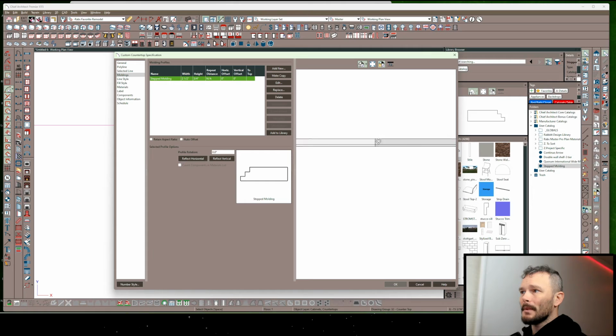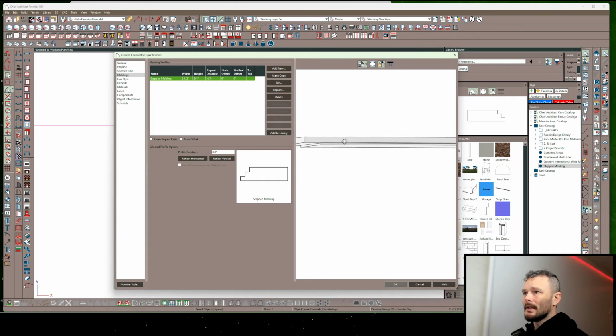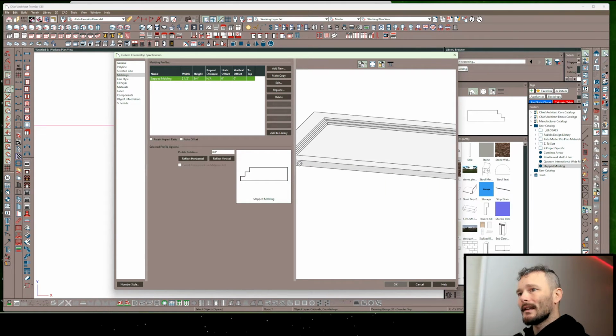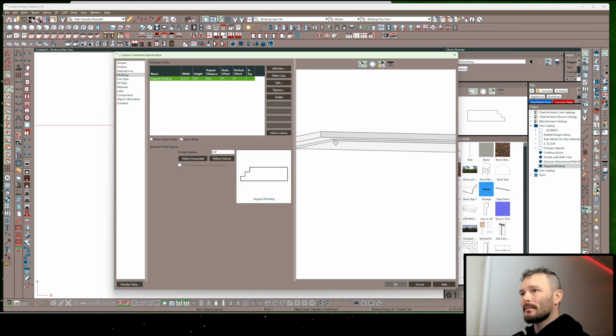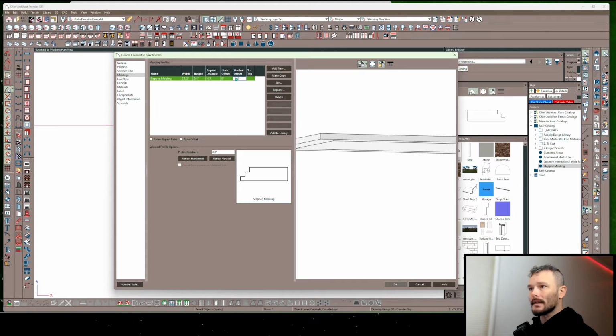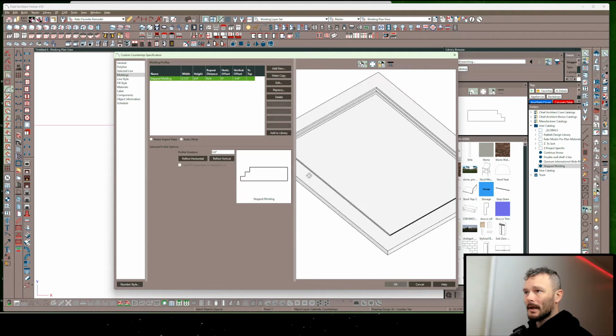That's to top. Instead, we could say to bottom. You can see that it's sitting proud of the panel itself. If you need this to be flush with the panel, you do a vertical offset of -1/4 inch in this case. Now it's a flush panel, okay?